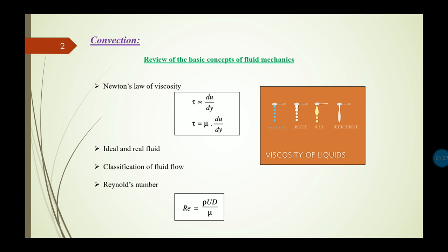If we want to define the term fluid appropriately, then we can say that all matter consists of only two states, fluid and solid. Now, a solid can resist a shear stress by a static deformation, but a fluid cannot. Any shear stress applied to a fluid, it may be negligibly small, will result in motion of the fluid. That means the fluid moves and deforms continuously as long as the shear stress is applied.